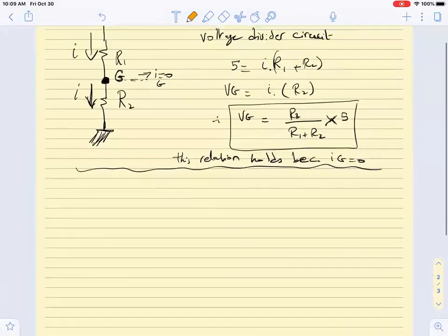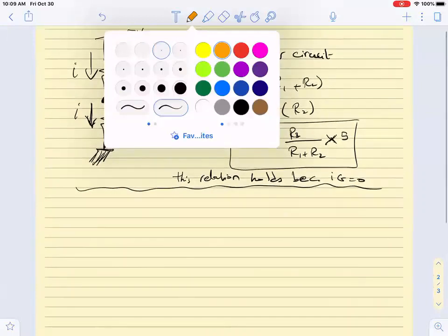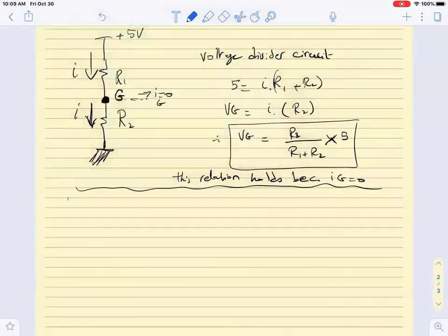So because the transistor is in saturation, I have the assumption that ID is half Kp times VSG minus the magnitude of VTP, all squared.